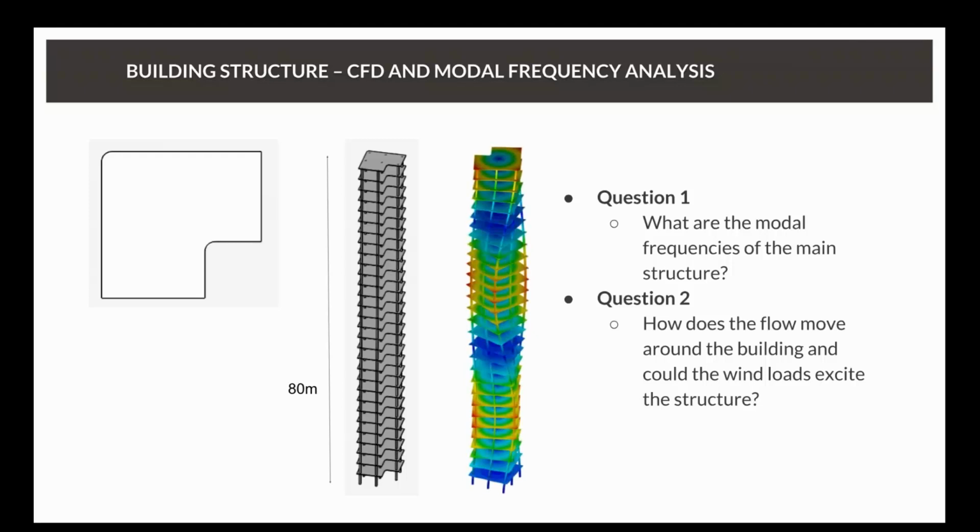So this is just an example of what one of the modes looks like from the frequency response analysis. It's shaded by displacement, so blue is not really moving much, red is moving a lot. It's really exaggerated, but it helps to paint a picture. So later on, if we decide that we do need to start changing the design, this will help us identify what we should change, where and why.